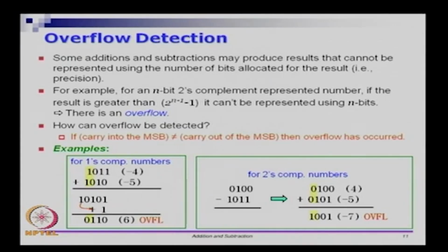Typically what computers do is, if something like that happens, the circuitry can detect this overflow and they will set a flag called the overflow flag. If you have done 8085 or 8086 programming and so on, they would have taught you about this set of flags that are there in the processor. So the addition or subtraction of two numbers can result in the overflow flag being set, which means the result that you have is not correct, because it is not in the range that is represented.